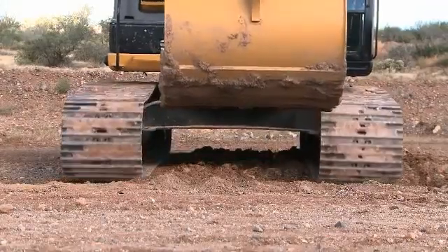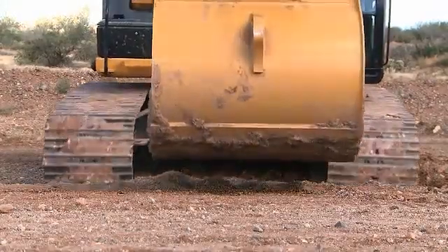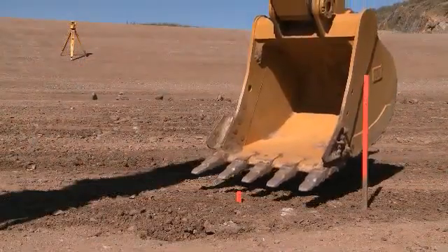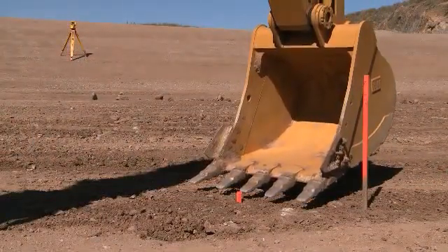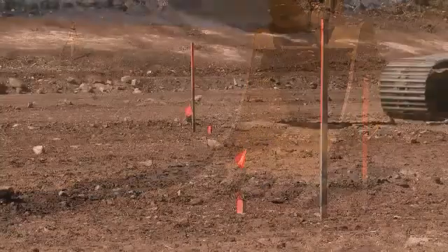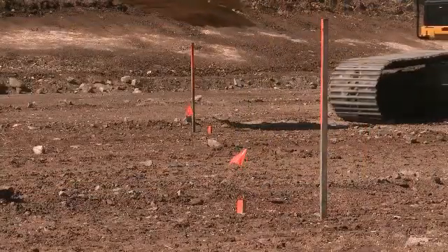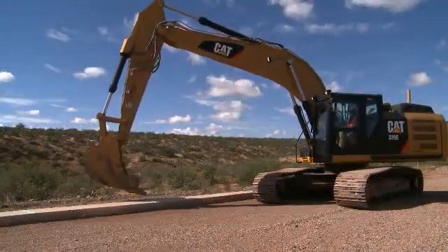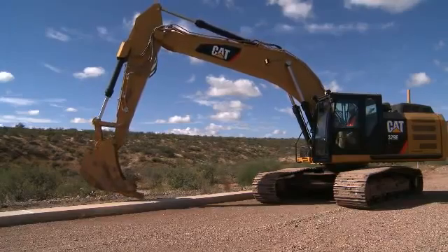When you move the machine undercarriage, the elevation of the machine will change. Rebench against another known elevation to adjust for the new undercarriage position. One method is to have a reference within reach for each new machine location. Another method is to transfer the reference point with the touch point feature.